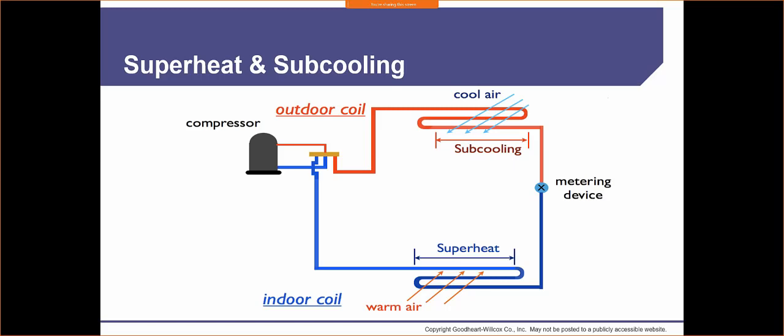Why? Because we're going to have a refrigeration effect happening outside of the system. We have 55-degree refrigerant, or whatever it is, traveling along this pipe, right? And in this diagram, we're actually running in reverse. So the refrigerant's actually flowing in this direction, going from a dark blue to a light blue. And what happens is we can still absorb heat even though we're not having warm air blow across it in the evaporator. There's still heat in the air inside the building. And if that warm air comes in contact with that 55-degree line or 35-degree line or whatever it is, well, we're going to start to get condensation, all right?